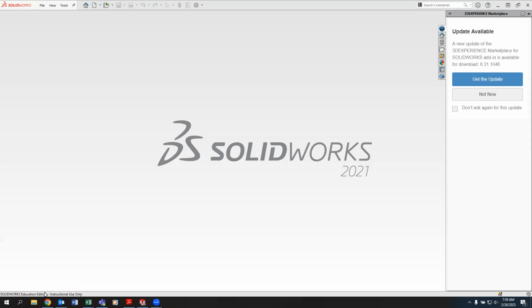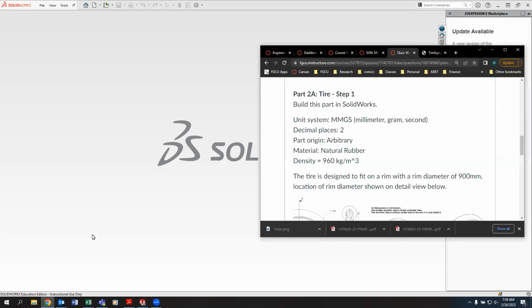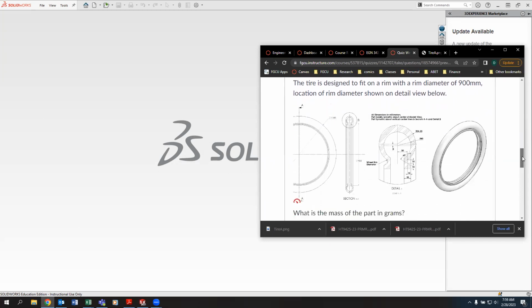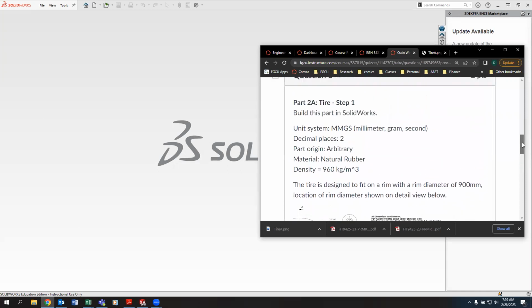Good morning, class. So today I'm making a quick video on this practice problem that we have for making a tire. And this problem focuses on the use of various Revolve extrudes as well as Revolve cuts. So let's start off by making a new part.